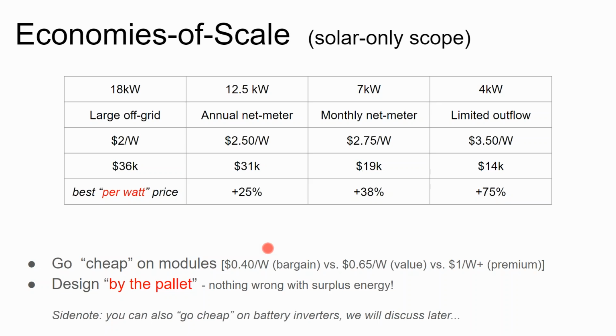When you buy a more expensive solar panel, you're really buying space efficiency. You're buying a smaller footprint. So in Mississippi, we don't need the smaller footprint. One thing about Mississippi is the rooftops are very plain and boring, and that means you can fit a whole bunch of rectangles on them. We don't have all these staggered roof lines that you see in other places. So it's very easy to fit quite a large solar array on top of a garage or a barn or a basic roof plane.